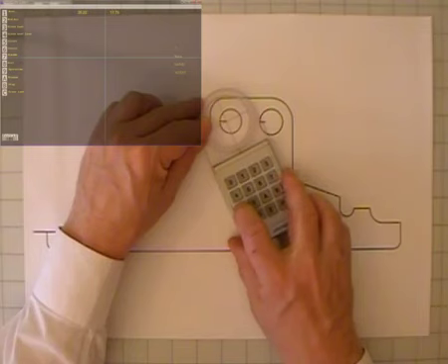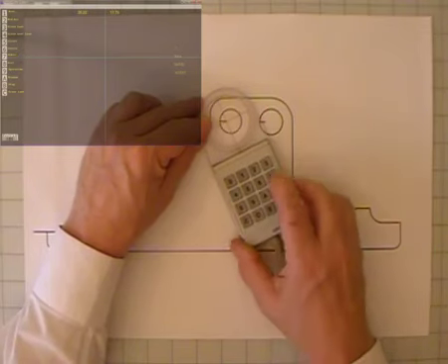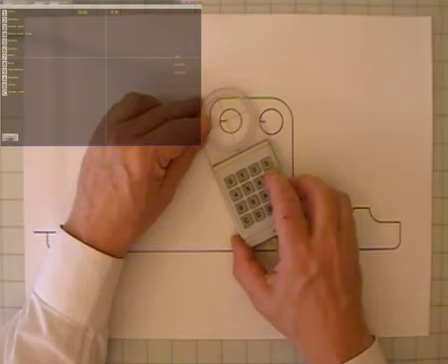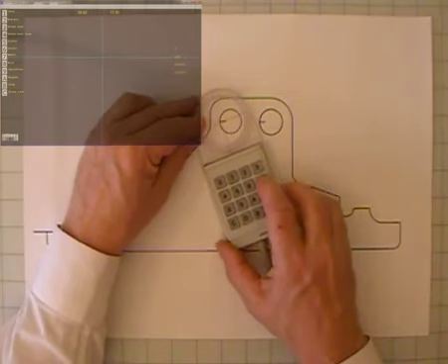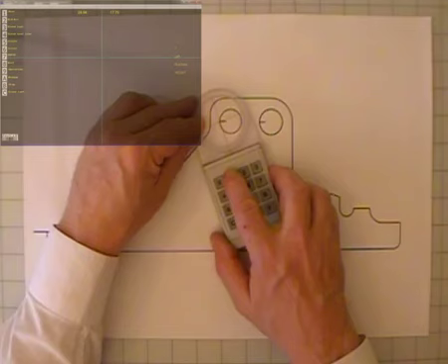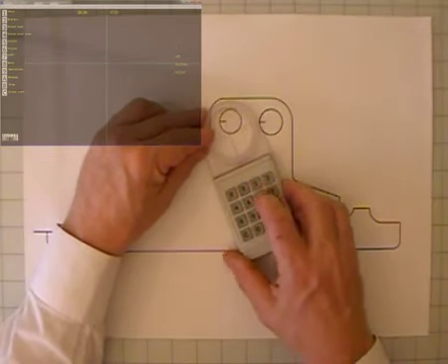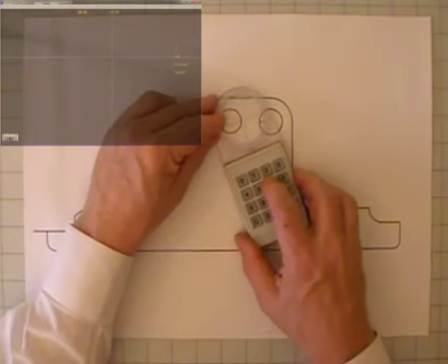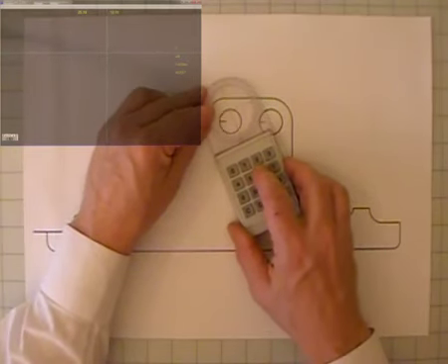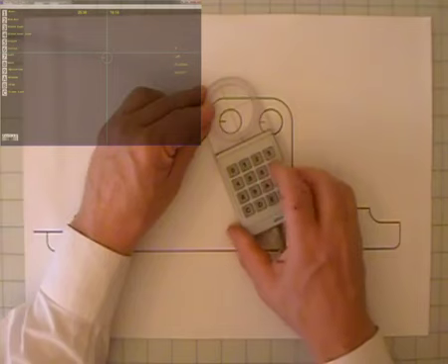Set the curve to left with button 8. Switch to cutting with button 7. You will see the screen change. You can have many processes, including line marking and drilling. To digitize the circle, pick 3 points with button 6 and the circle appears. Of course, like other constructions, it cannot appear until you have selected all 3 points.